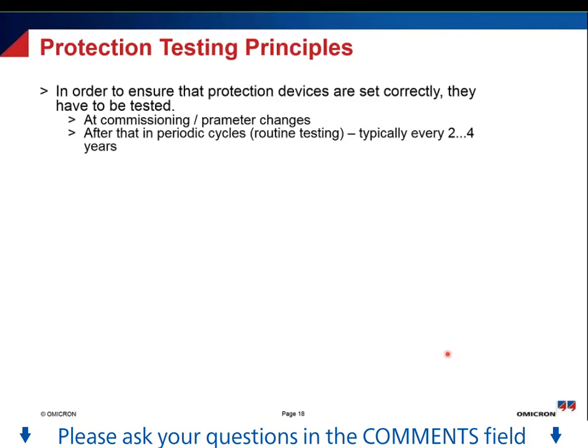That is a very, very challenging problem for the protection relays, and you typically don't find out whether something goes wrong until you have a fault and something really goes wrong. So you don't know if a relay is not working correctly anymore. In order to avoid misoperation during a fault, you need to test the relays.